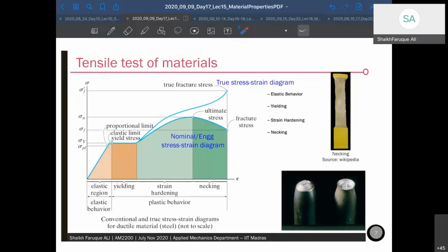For rubber, if you pull it, you can go a longer length and you will see that it comes back to its original configuration, right? So this part is called the elastic part. So within the elastic zone, if you load the material and leave it, it will come back to its zero configuration. But once you cross the elastic zone, you go to the plastic and leave the material, you unload the material.